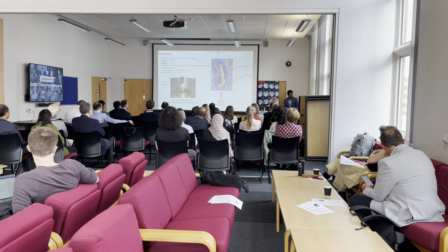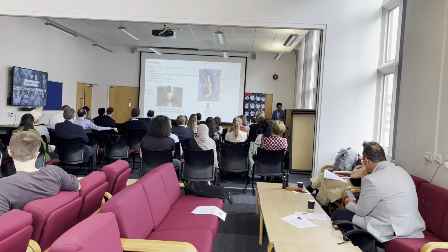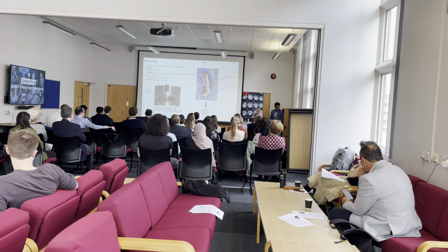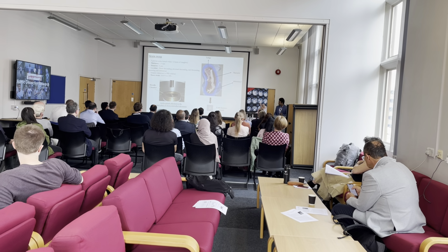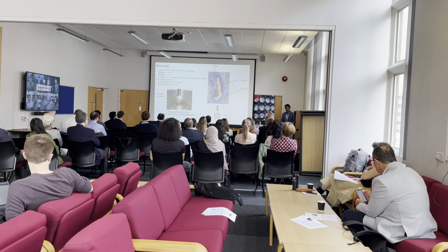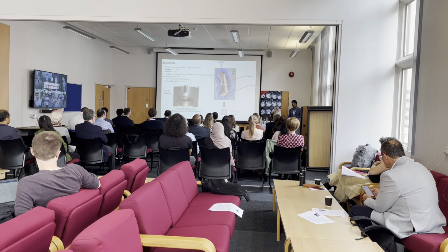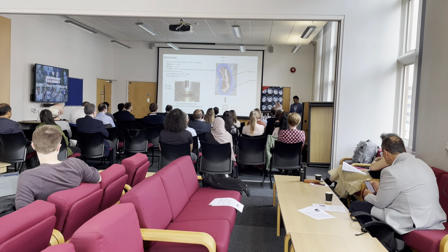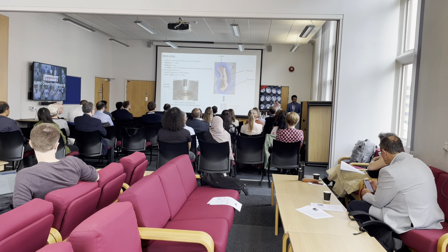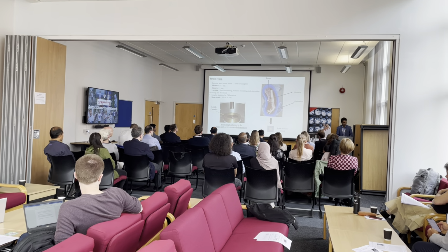Now, how this particular setup works is that you have a stress controlled oscillation in which you apply a torsion, some sort of a torque, to the cylindrical samples of the aorta. And as a result, the cylindrical samples apply a reactionary torque. And that particular reactionary torque is nothing but the storage modulus. That is the amount of energy that is being stored in the sample. The amount of energy that is being dissipated is also measured as something known as the loss modulus.